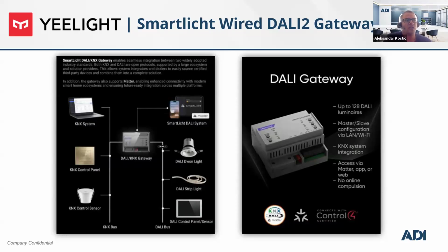It also has a KNX interface built into the device itself. But keep in mind that this KNX interface does not support IP routing gateway functionality. It is just providing a bridge between KNX and DALI. So you can import KNX devices and control them through this gateway. But the setup of the KNX line itself would still require an IP routing gateway.